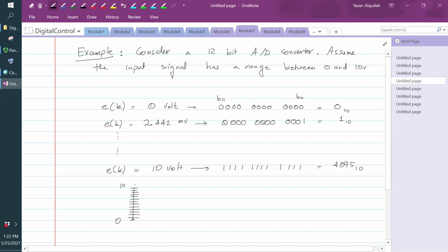And this is what quantization does. And I imagine everybody is probably familiar with that and have seen this. Okay, now what happens if I look at this, just to understand where the error comes from? What happens if I have a value that I sampled that is 0? We assign it as 0. If it is 2.44, we assign it a 1.